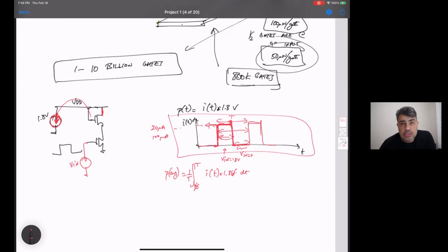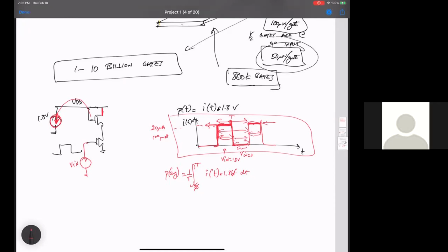What I would do is, somebody mentioned that LTSpice or maybe PSpice outputs average power, or just plot out the instantaneous power. If you want to eyeball, it should be pretty flat. If you don't see a flat or relatively flat value here, something's probably off. So it should be getting stabilized, and you can just read that multiplied by the amount of time that it is on, and multiply the off value also by its amount of time, and average those. Got it.